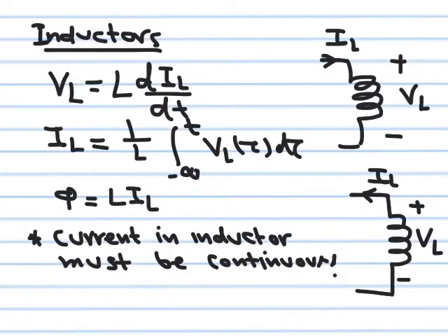We start first maybe by discussing what's an inductor. An inductor is a component that's usually made of a number of turns of a coil. We call it a coil. So we have a wire and you create from that a number of turns. When a current flows in this coil, it creates a magnetic field in its volume. So you can get a strong magnetic field. It's not an electric field like a capacitor. It's a magnetic field flowing inside the volume of that coil, and this magnetic field will store energy, but this energy is stored now in the form of magnetic energy.